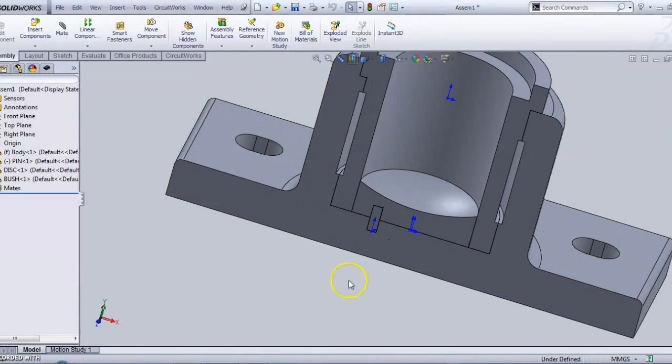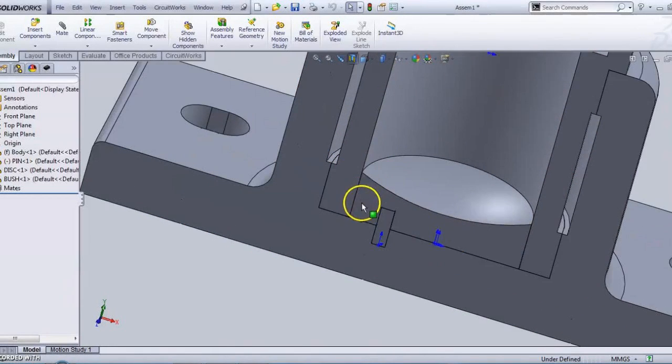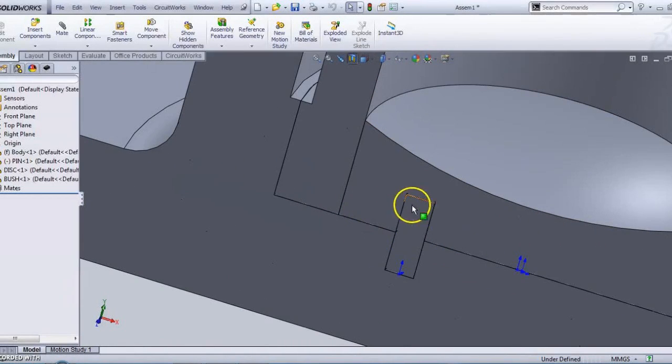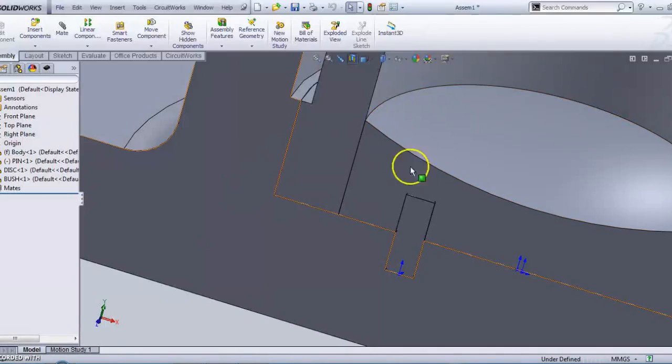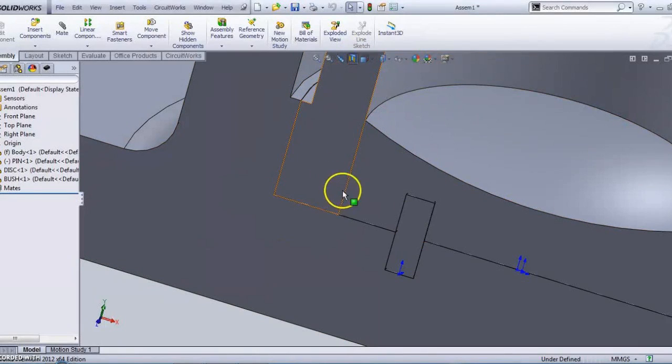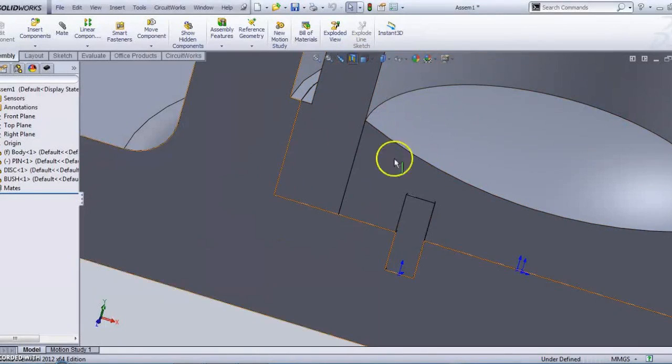Okay, so this thing we have to validate each and every time, because most of the time it is not possible to get all the parts correctly assembled. There might be chances of missing one or two dimensions. So this can be verified in the sectional view. Okay, so everyone must have habit to see all your corrections in the sectional view.